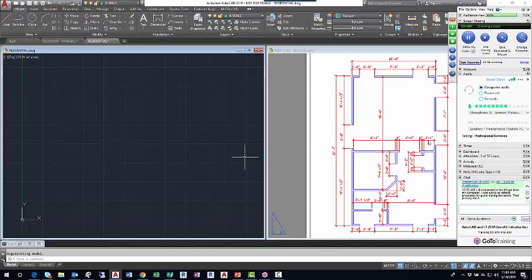I'm going to be drawing walls for the majority of my time, or at least the beginning phases of this process. So I'm going to make sure the A wall layer is current. If you had any layer other than A wall current, you could click the little down arrow on what's called the layer window, or layer control window, or layer control. People use a few different terms for this window. Left click the name of the layer you want to be current, in this case A wall, and now your A wall layer is current.